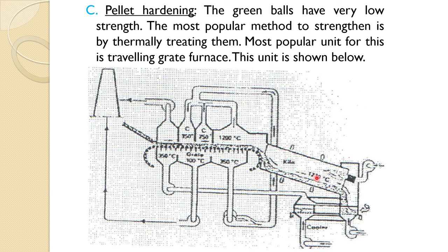from this to this journey, the induration of the pellet with fusion occurs and the change in phases occurs, and as I saw in one of the slides previously, swelling of the pellet occurs. So, all those mineralogical changes may come, and that is why it is necessary to have proper control of the raw material. Swelling should not occur, otherwise this will create a problem in the blast furnace permeability. So, once it comes through the kiln, the pellets are totally indurated and come out, and here the